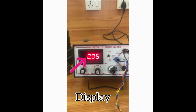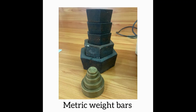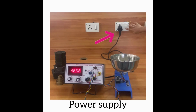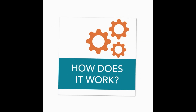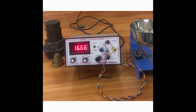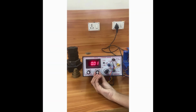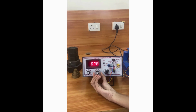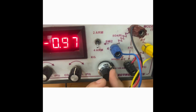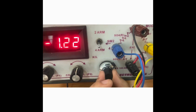Now moving on to the apparatus of strain gauge. It consists of a display unit, gauge factor knob and a Wheatstone bridge on the front panel, metric weight bars and a power supply. Now let us know about the working of the strain gauge. First of all, we should switch on the power supply, then we will see the values on the digital display unit. The next step is we have to calibrate the device by adjusting the knob which is present below the display unit. Then we have to set the gauge factor by adjusting the knob and make the gauge factor 1.